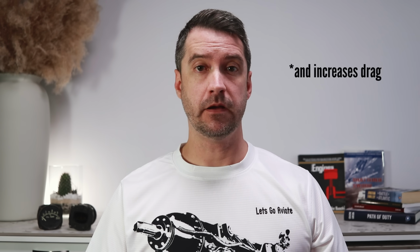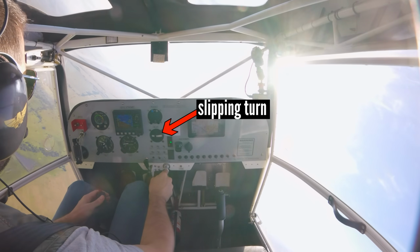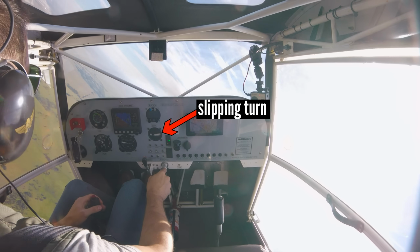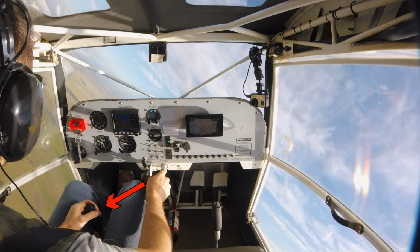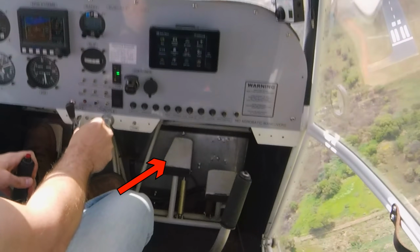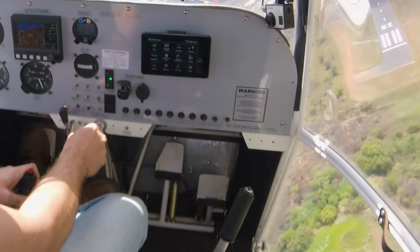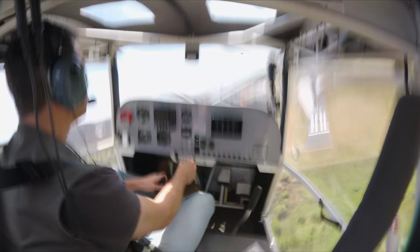Instead, uncoordinated flight reduces overall lift, which causes a descent. To counter that descent, the pilot needs to apply more back pressure on the controls, just like trying to maintain altitude in a turn. And as we've already said, that increases angle of attack. Increase it enough and the wing stalls. Still not convinced? Consider a full rudder forward slip on final approach. It's as uncoordinated as it can get. Yet it doesn't stall the airplane.